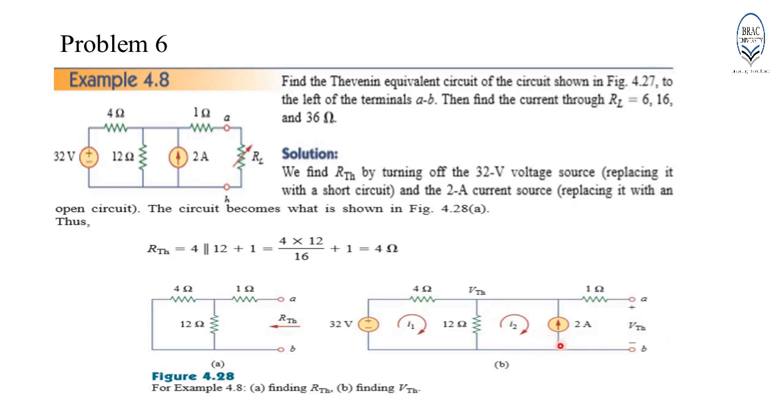We can determine the potential drop across the current source by applying mesh analysis in these two complete loops. There are two unknown currents, hence there will be two linear equations from these two meshes.